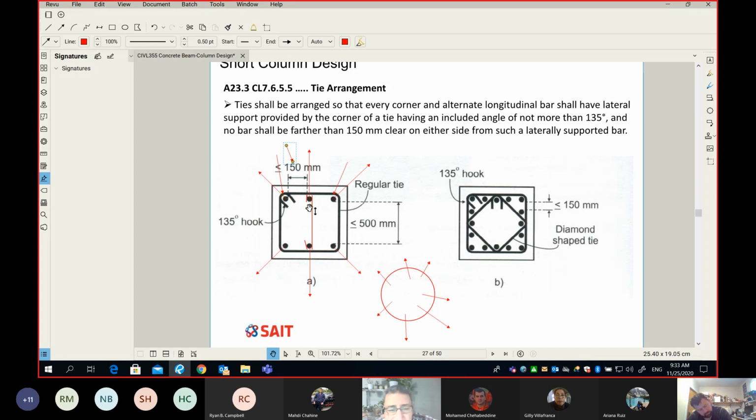It means it cannot do anything to help this bar here from buckling to the outside. So bottom line is, when this is so long, it means it's very weak, and then we have to add this red extra piece. The secret number is 150, which means if we're able to estimate this number, which is not really a super science, it's based on geometry, I'm going to show you in a minute, then if it's less than 150, then it's okay. Our tie is short enough. It can simply stop this guy from going outside.